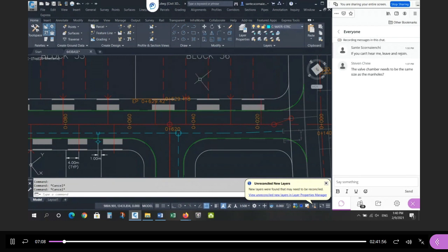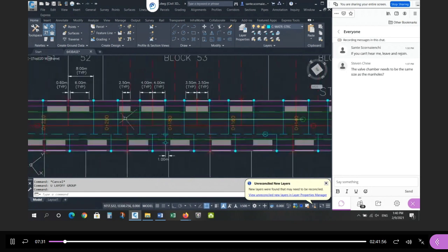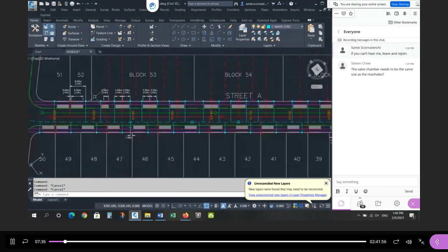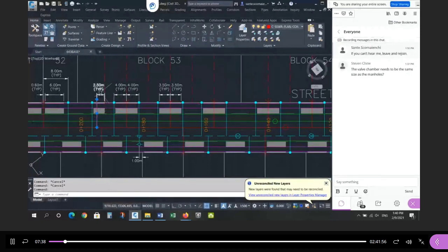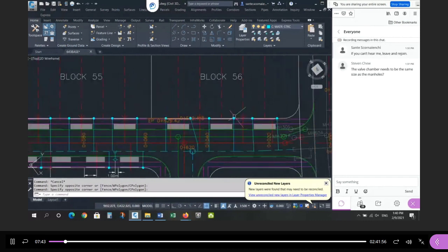Okay. So I left the driveways paired, but I offset where I put my typical shared connection. I put them on these lot lines between the driveways instead of on the driveway. Okay, so now I have two singles. And then you might say, okay, you've got to label those. Yeah, but I did this once before. On this block 53, there is an odd number of lots. So I did have to have one single service connection. I labeled it 250 typical. So anytime you see a single on a townhouse, you know it's 250. So I don't have to label this one and this one. And that's what the typical does for you.